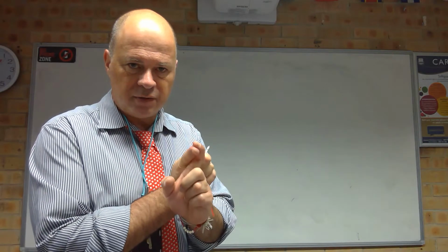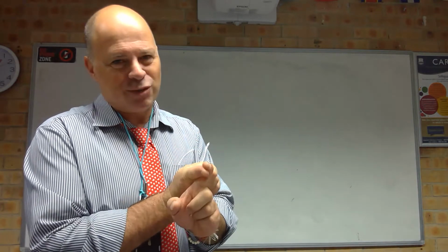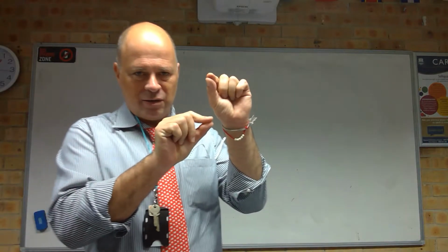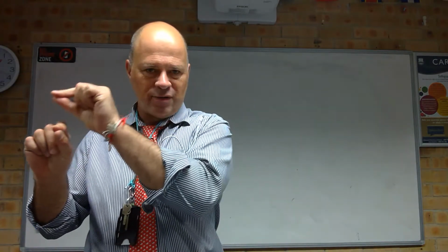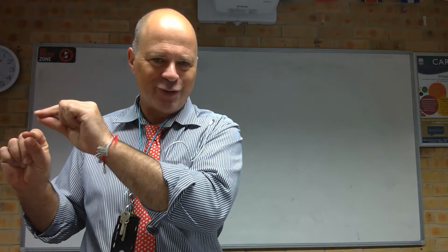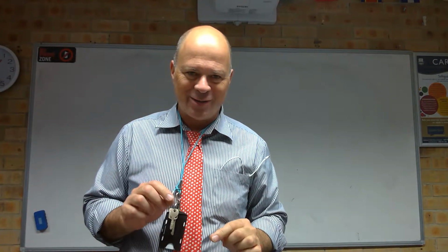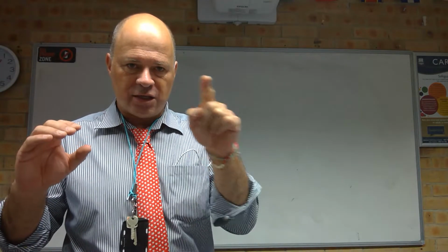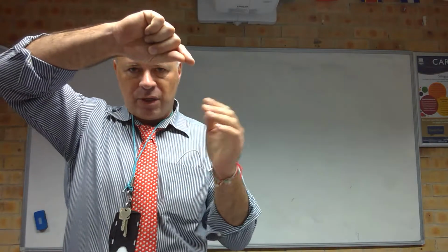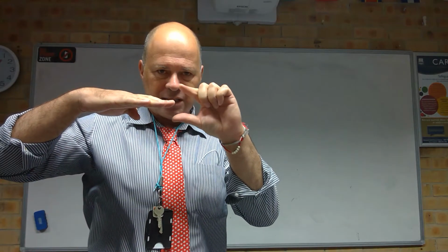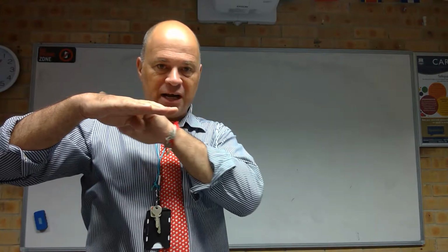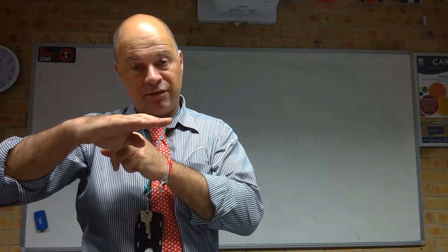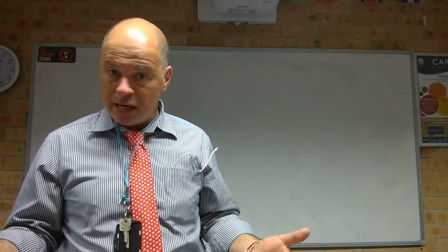Classic theory, which involves Bernoulli's principle, which used to rely on the equal transit argument, which is actually incorrect. The idea that the wind is flowing over the top and the two particles have to arrive at the same time. Sort of a weird take on quantum entanglement, which doesn't happen with air particles. So we actually know from wind tunnel testing, which is one of the videos that I gave you, that top flow, if you have a particle arriving at the big, if this is your wing and your particles arrive at the same time, this top particle is actually going to flow faster. It's going to arrive at the end of the wing before this bottom particle. So it's actually flowing much faster, which is why we have lift generated. So it is obeying Bernoulli's principle.